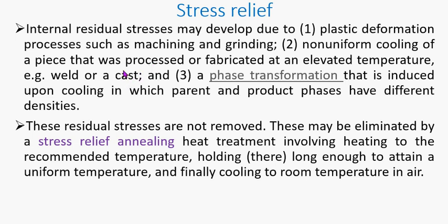So during the solidification of the molten metal, if there is non-uniform cooling, this can also cause internal residual stresses within the component. Or welding: during cooling, if the cooling is not properly monitored, it can also cause internal residual stresses to be